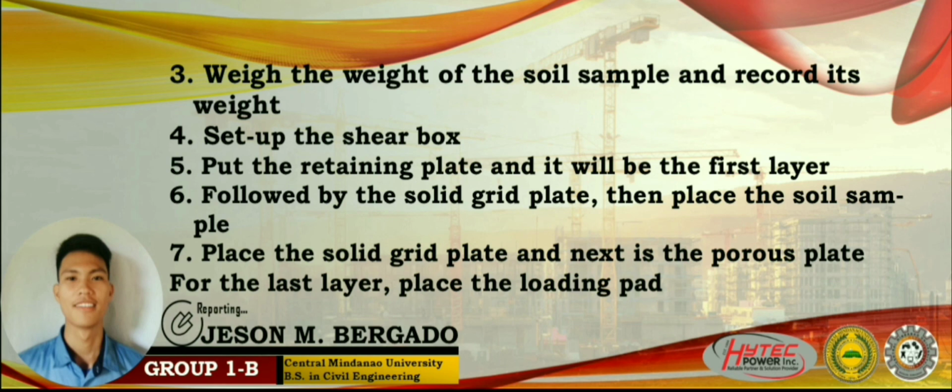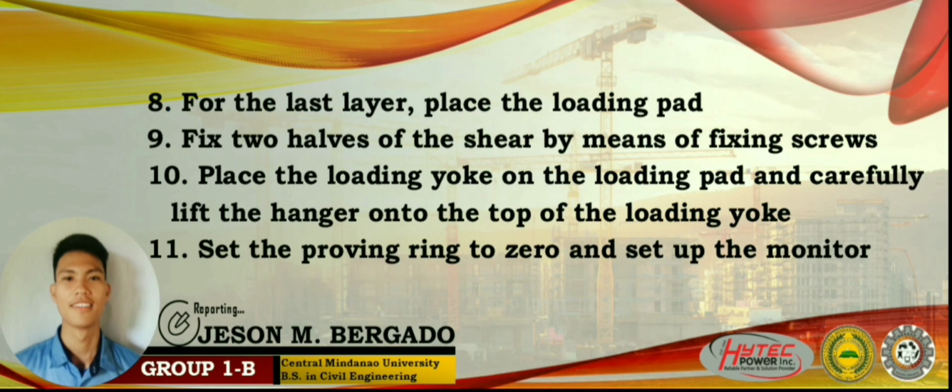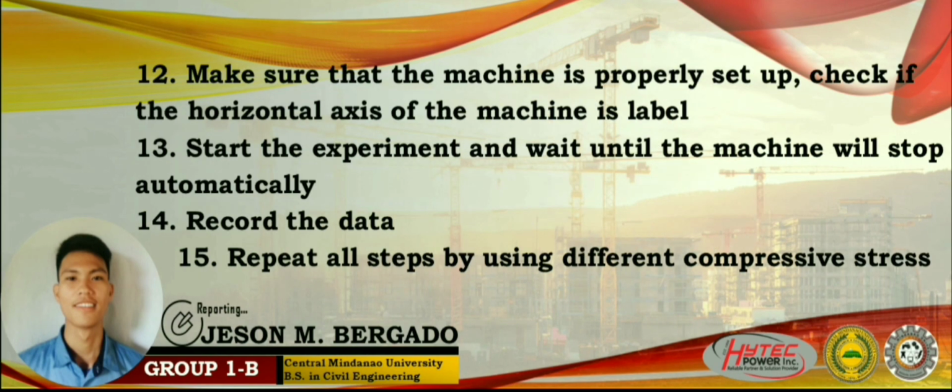So sa pag-set up ng shear box, just follow the procedure. And then sa huling pag-set up ng shear box is place the loading yoke on the loading pad and carefully lift the hanger onto the top of the loading yoke. Set the proving ring to 0 and set up the monitor. Make sure that the machine is properly set up.